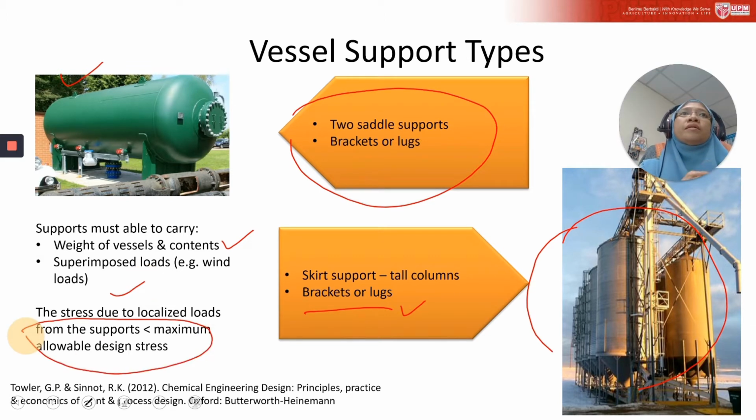Another thing, normally we have manways at the bottom of the vessel. So you must take into consideration that the support design will allow easy access at the bottom of the vessel, where normally there is access for inspection and maintenance.